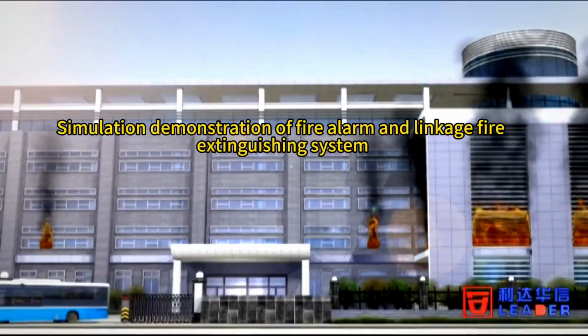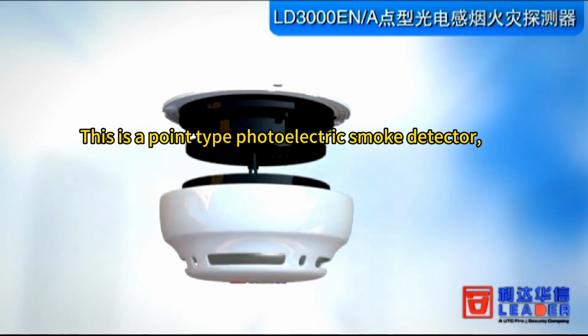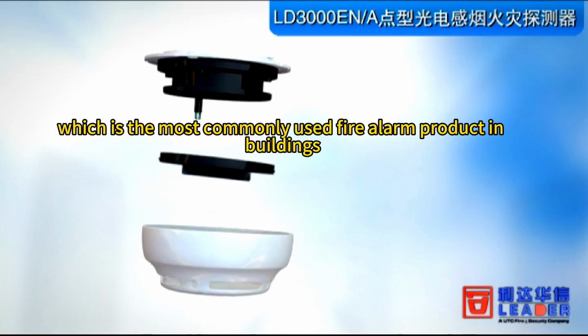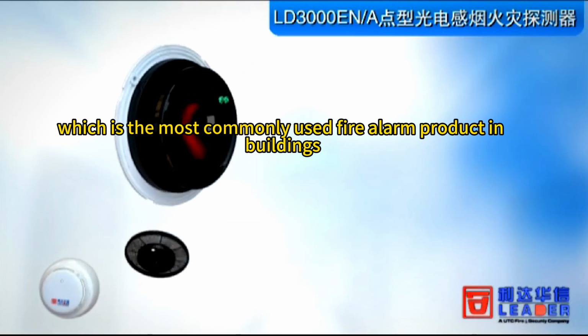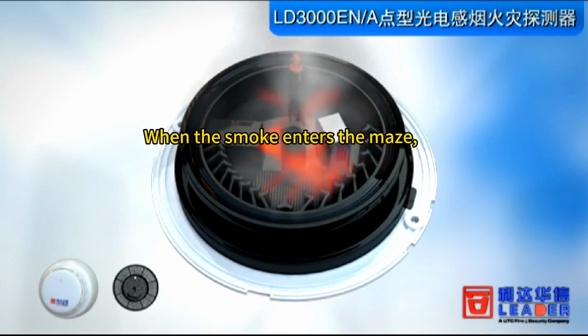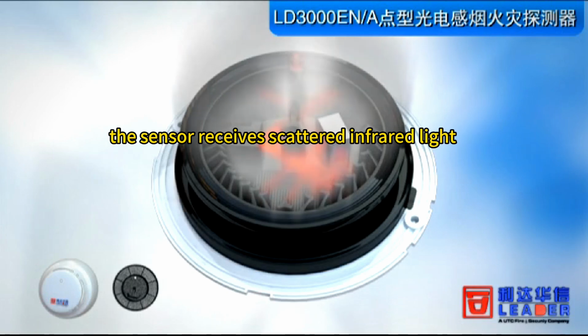Simulation demonstration of fire alarm and linkage fire extinguishing system. This is a point-type photoelectric smoke detector, which is the most commonly used fire alarm product in buildings. When the smoke enters the maze, the sensor receives scattered infrared light.